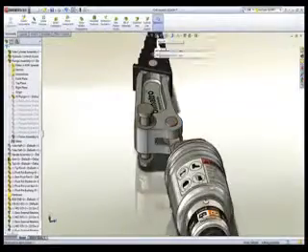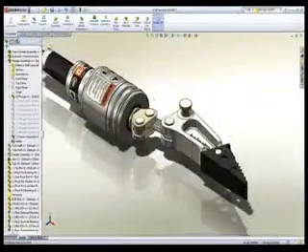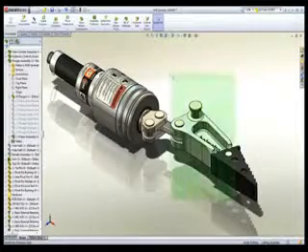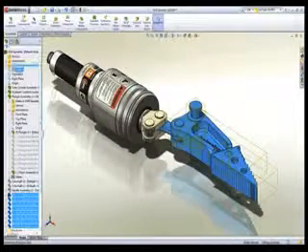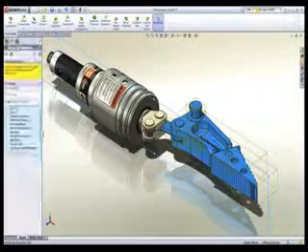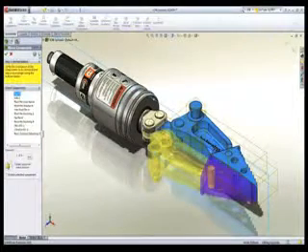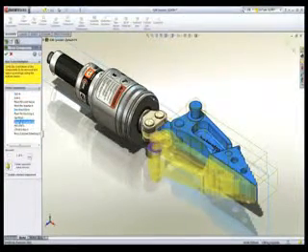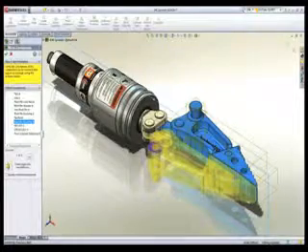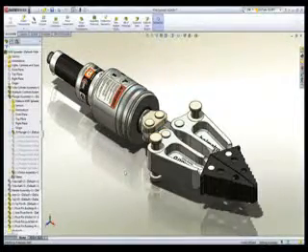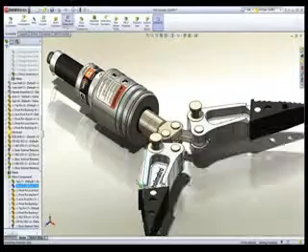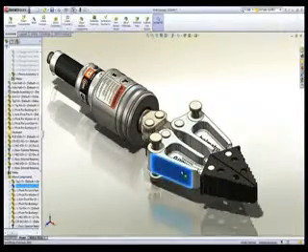Half of the spreader is complete, and we can save assembly time by mirroring the parts about the central plane to the opposite side. SOLIDWORKS allows us to verify and change position of each part, and even to create opposite-hand versions of individual parts. In just 2 minutes, there were 19 parts added to this assembly, and our assembly task is complete.